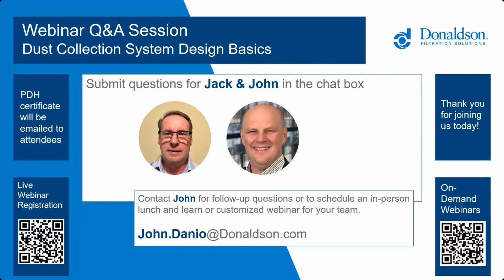All right. So our next question, do you have any recommendations? Now, this is a little more specific one, Jack, for dust collectors and filters for carbon black in a tire facility. Okay. With tire facilities, it depends on the process. Is this after the vulcanization process, or is this before the mixture of the material going into it? If it's on the front end before the vulcanization, then you're not going to have as much hydrocarbon issues, and therefore you can potentially look at cartridge collection,